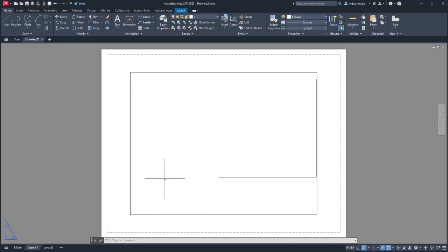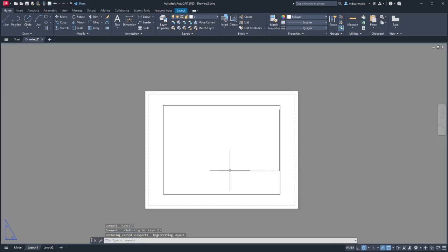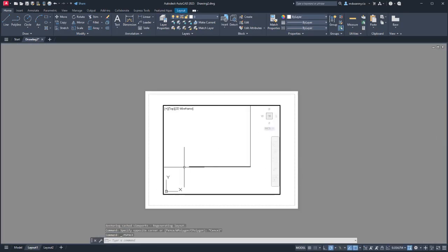In case you did get stuck in here, something that I guarantee will happen to every single one of you at some point in the semester is you'll be working here in what's called paper space. This right here is model space. This is where you set up your drawings. This is paper space. So this is a window, a viewport into model space that you'll actually use to set up your floor plans for print.